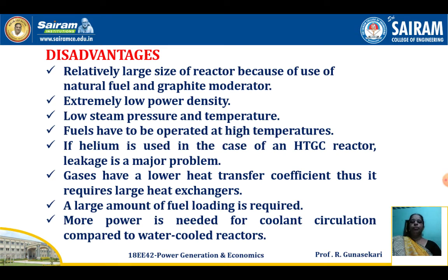Fuels have to be operated at high temperatures. If helium is used as a coolant, leakage is a major problem. Gases have a lower heat transfer coefficient. It requires large heat exchangers. A large amount of fuel loading is required for gas-cooled reactors. More power is needed for coolant circulation compared to water-cooled reactors.